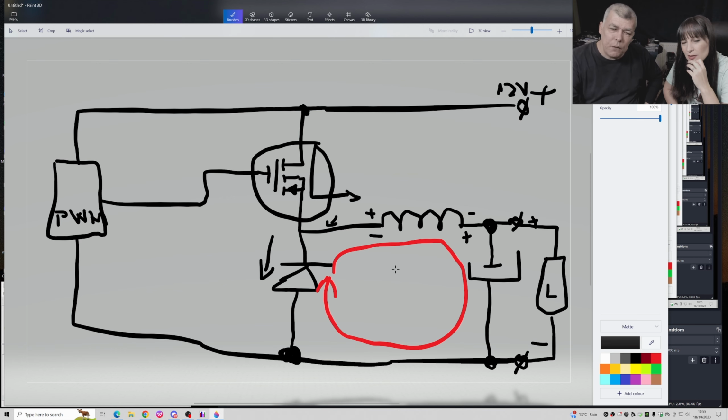People think, okay, so it's boosting. So how is it boosting? We're charging with plus and minus, right? How is the coil charging with plus and minus? Where is the minus? You have a capacitor which doesn't allow DC flow, right? So where do you get the minus from? People think the minus is coming from the load.